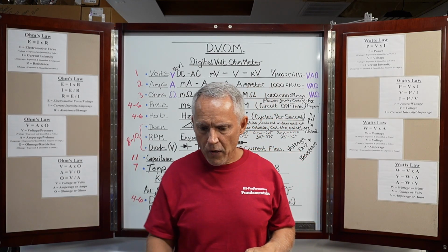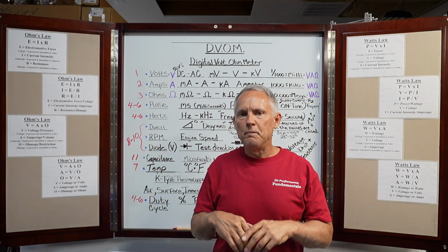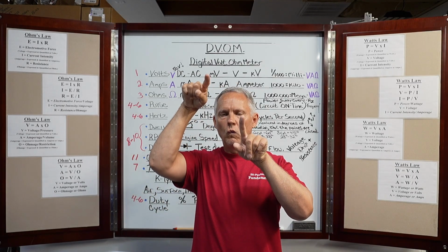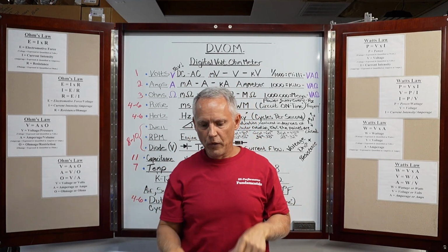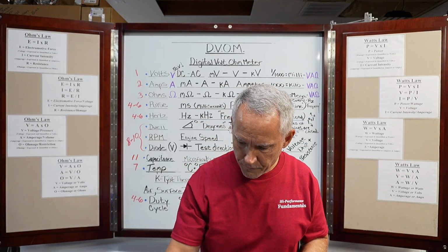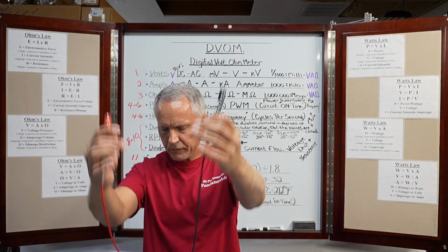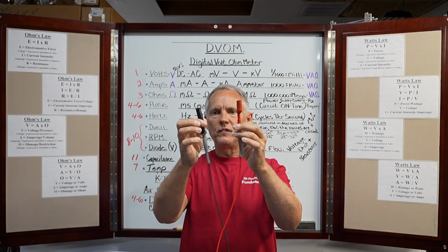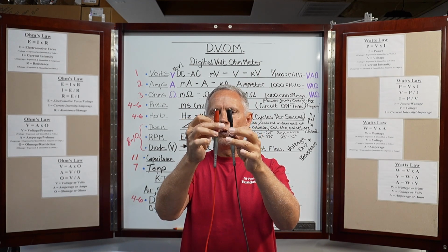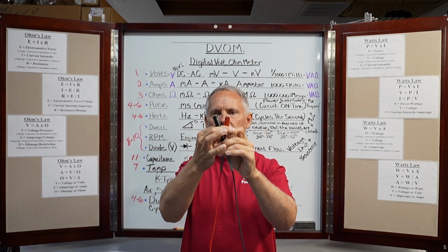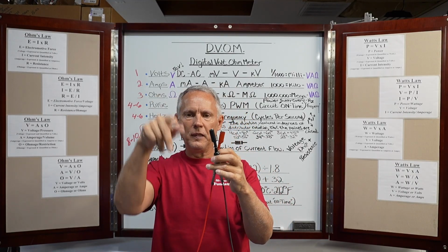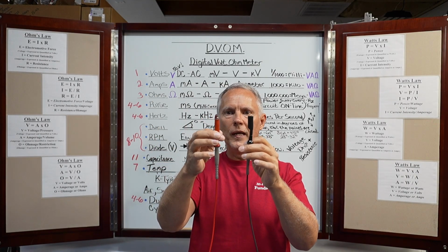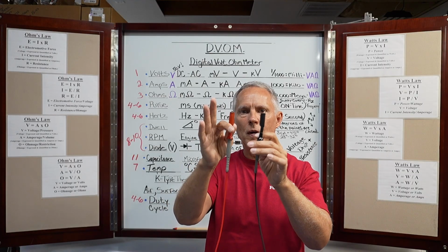So for example, if you have a light bulb, and the light bulb has two terminals, one going into the filament, one coming out of the filament, two terminals. You will take your ohm meter, put it on the ohm scale, and you will touch those two terminals just like that. And it's not polarity sensitive, right? It can be done either way on a bulb, right? So let's say you have a tungsten filament bulb, right? And you come up with whatever you come up with, right? Three ohms, whatever it might be, right?